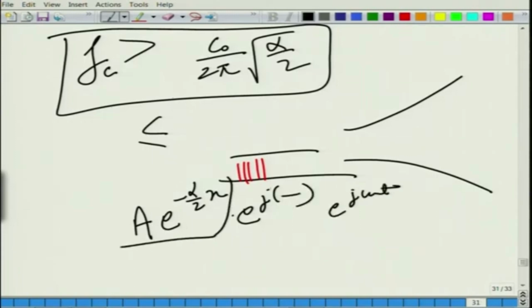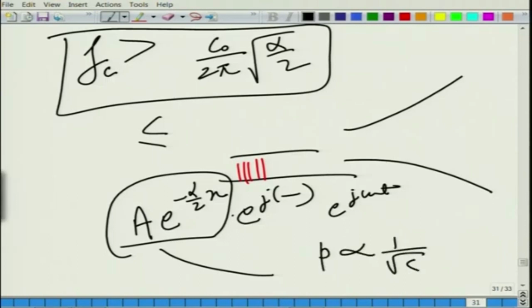This is the A x function that I was talking about, a decaying function with respect to the space x. Similarly, you can derive the phase relationship between the velocity and the pressure, and the phase velocity. We can get the amplitude of the RMS acoustic pressure field, and show that for an exponential horn it is decaying approximately as 1 by root s.